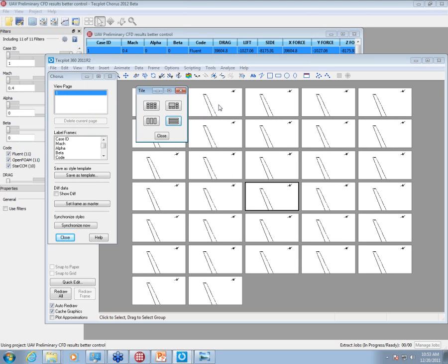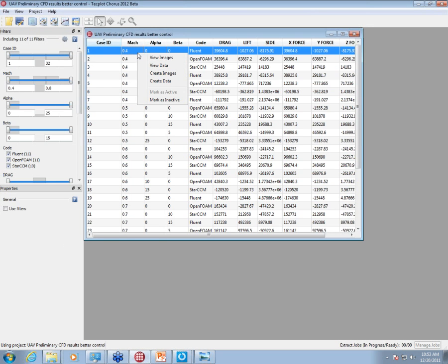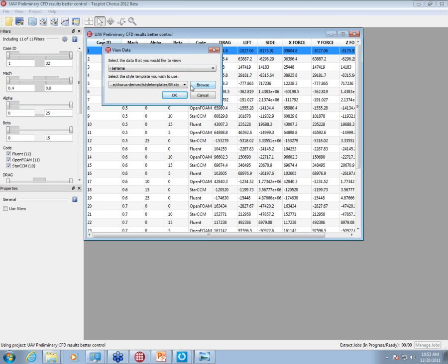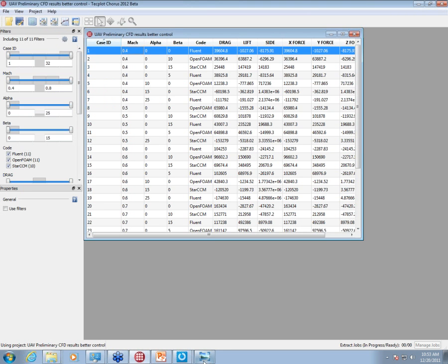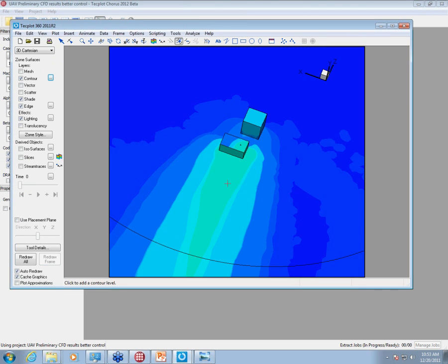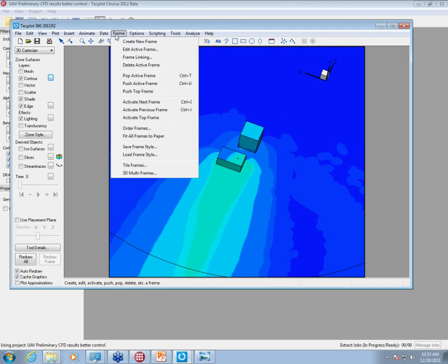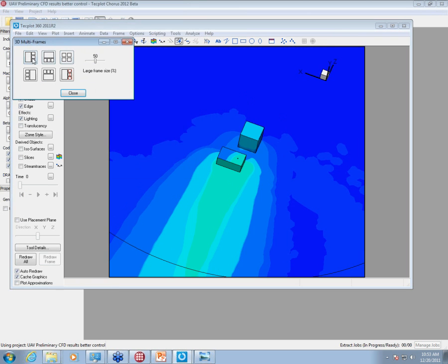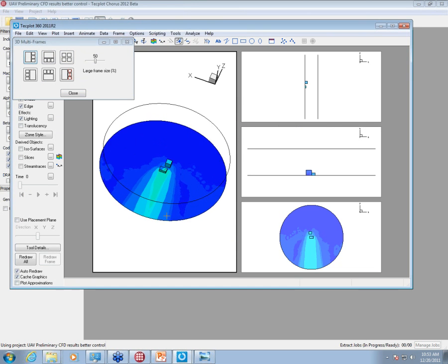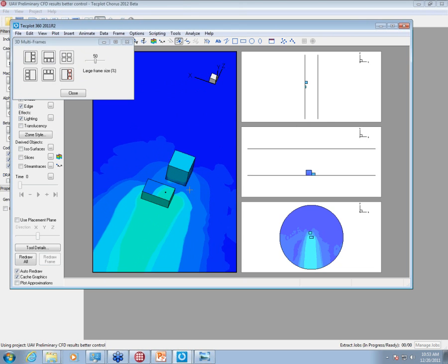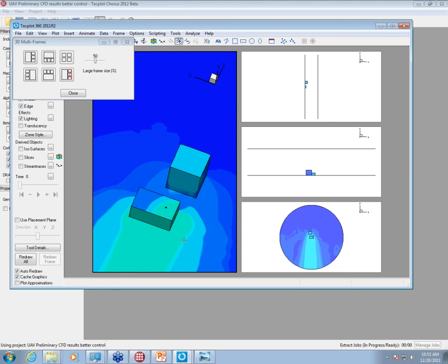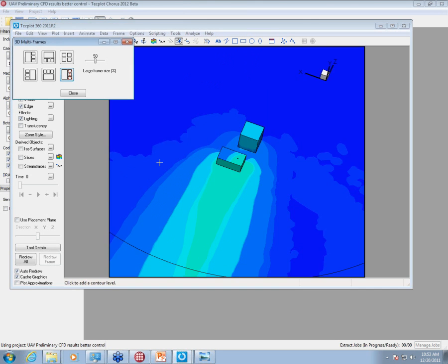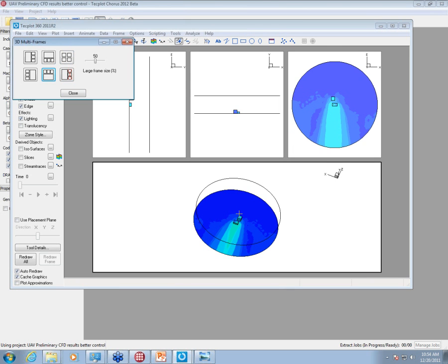The other thing that it allowed you to do, if we just go back to one result, and without a template, okay, well, even on this one, it's fine. The other thing that it added was the ability to do projected views. So now we're looking at the principal views, the XY, the YZ, and XZ. So traditional engineering plotting. It simplifies that process quite a bit, and you can go right back to your initial view. You can also play around with how it's done.